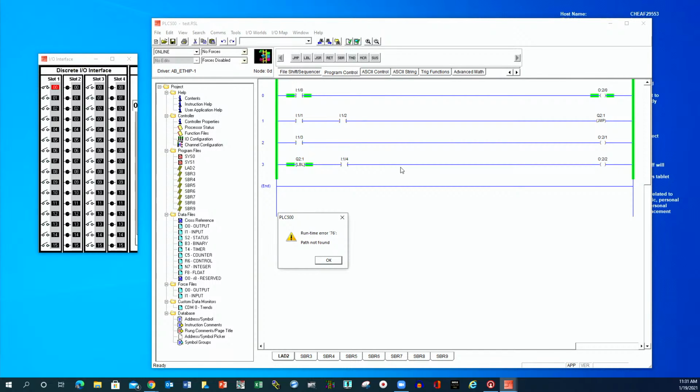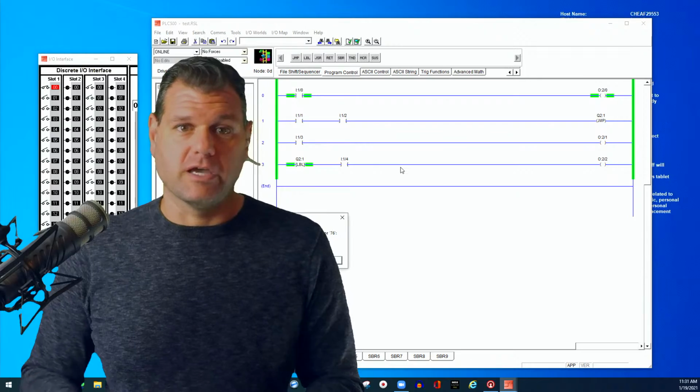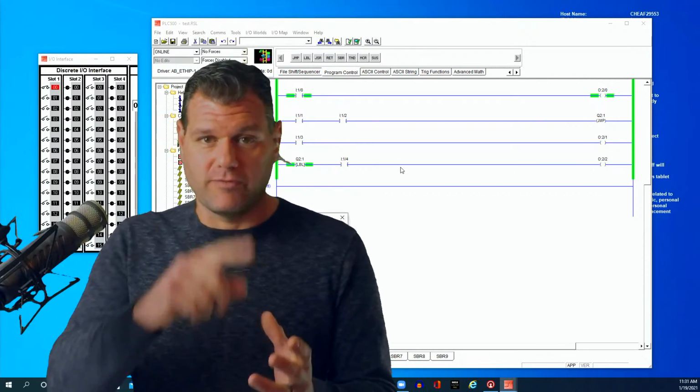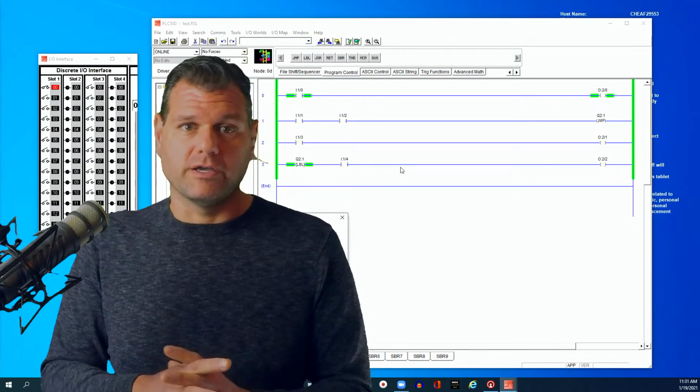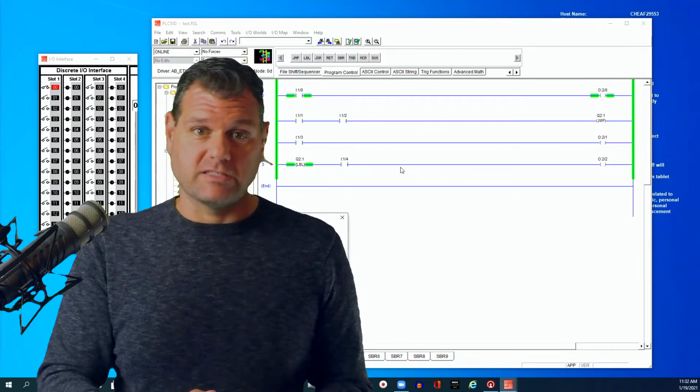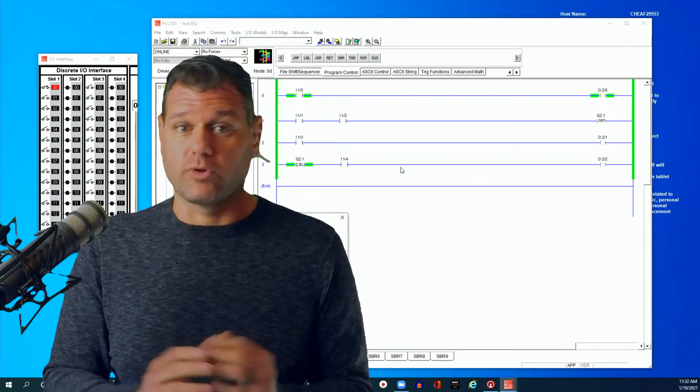You just have to be very careful not to put yourself in a loop, because if you're in a loop, it will slow down the scan process, and then something called a watchdog timer, which is like the master timer for the whole program, will eventually kick in and say, something's wrong, I'm going to shut it off, and you have a fault. So if you have it just constantly going in a loop, it's going to mess up. But you can jump backwards and scan something once again before the end of the scan.